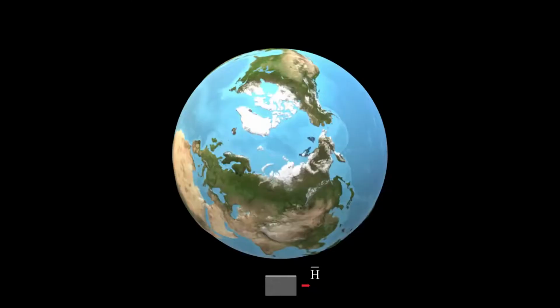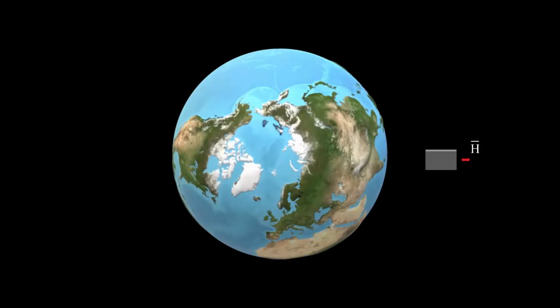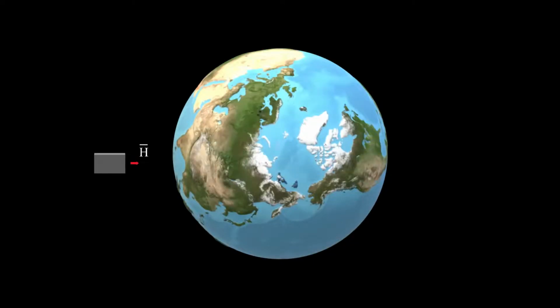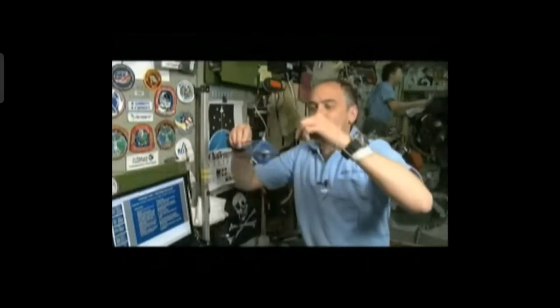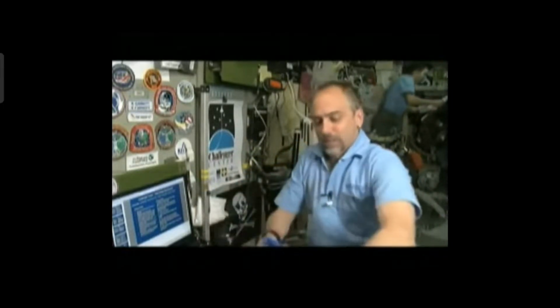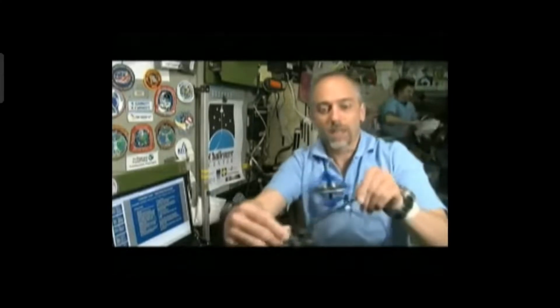When a mass starts to spin, its angular momentum vector remains stationary in inertial space. For example, let's spin a gyroscope at 6 a.m. with its angular momentum vector pointed at some convenient inertial reference. We can then observe how conservation of angular momentum works to keep the gyro always pointed in the same inertial direction. In this case, the angular momentum vector h appears to track a fixed point in inertial space. As the gyro sits in its stand, it looks like it's rotating throughout the day, but actually the stand is moving as Earth rotates, and the gyro remains stationary in inertial space.